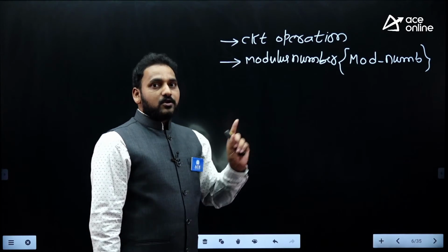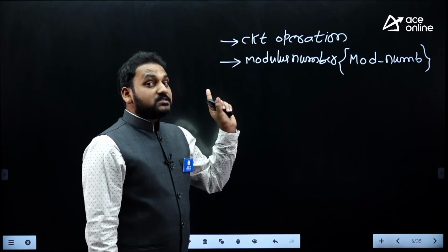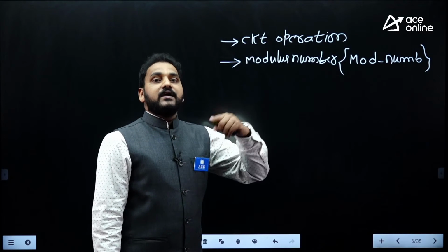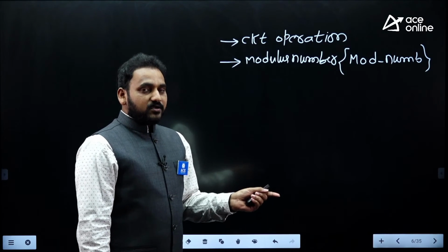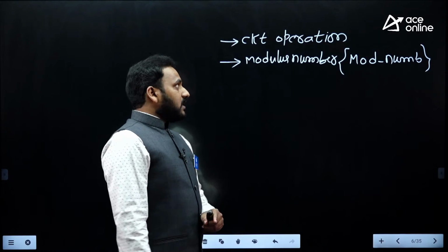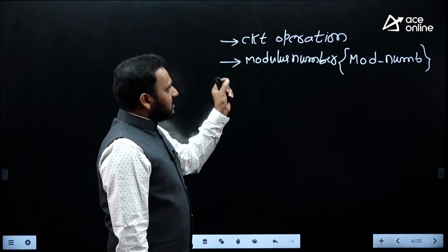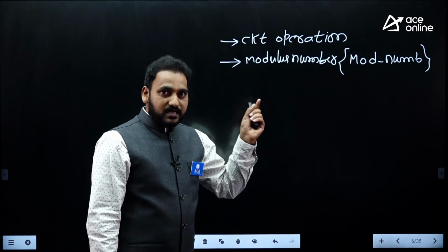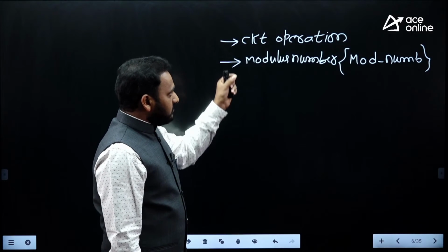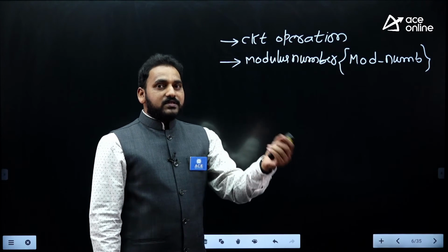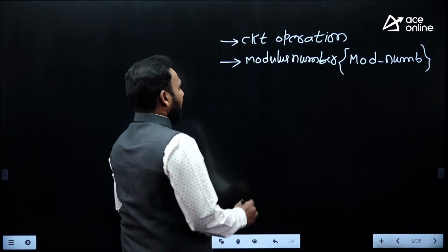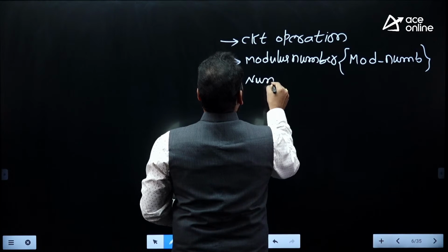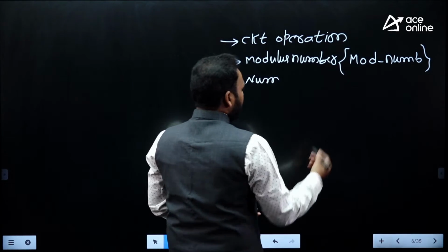It will play a vital role. Modulus number will play a vital role in the entire counters part. I said entire counters part, it means in both synchronous as well as asynchronous, so that you should understand the detailed meaning of modulus number in spite of the counter, maybe synchronous or asynchronous, and how it would help us while solving the problems. And the number of flip-flops required to design a particular counter, or a mod 10 counter, or a mod n counter.